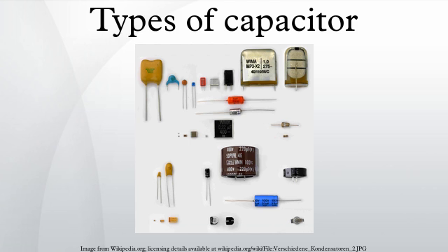AC loads can occur in AC motor-run capacitors, for voltage doubling, in snubbers, lighting ballast and for power factor correction, PFC, for phase shifting to improve transmission network stability and efficiency, which is one of the most important applications for large power capacitors. These mostly large PP film or metallized paper capacitors are limited by the rated reactive power VAR. Bipolar electrolytic capacitors, to which an AC voltage may be applicable, are specified with a rated ripple current.